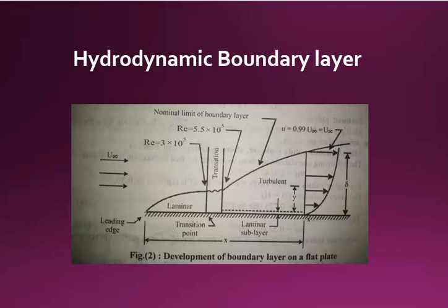Subsequently, the laminar boundary layer becomes unstable and the laminar flow undergoes a change in its flow structure at a certain point called the transition point in the flow field, where in the transition zone the flow is unstable and is referred to as transition flow. After going through a transition zone of finite length, the boundary layer entirely changes to a turbulent boundary layer. The turbulent boundary layer does not extend to the solid surface. There is an extremely thin layer called the laminar sublayer, wherein the flow is essentially of laminar character. Outside the boundary layer, the main fluid may be either laminar or turbulent.